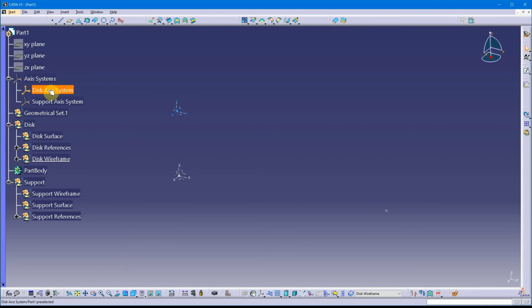I also have an axis system specifically for what I call a Solidify group. So the Solidify group includes the geometric sets that will eventually lead to a solidified surface that turns into a solid, and then an axis system as well. So you can see on the screen, I've gotten this started already. I've got my geometric sets created. I've got my primary geometric set, and I've got my secondary or subgeometric sets.